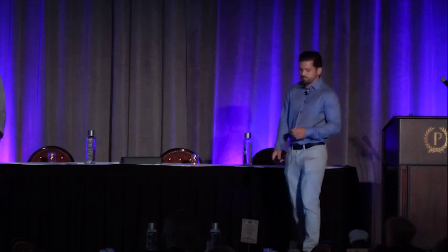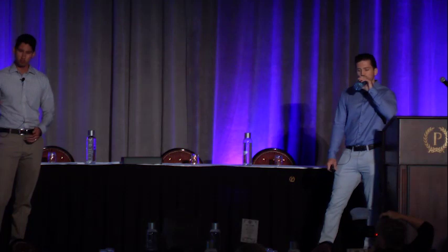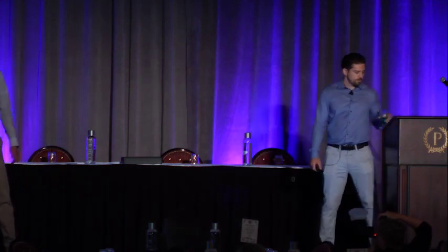So miscellaneous shoring is basically any sort of temporary shoring that's not really a structure or a building. Usually it takes the form of equipment that's being supported during repair or during installation. Because a lot of this stuff is not really a building, it's proprietary equipment, things like that. The first thing you're really wanting to do is talk with your client and get just a good idea of what kind of weight they're asking you to support. Then you'll be able to figure out what kind of equipment you want to use and what the configuration of your tower is going to be.